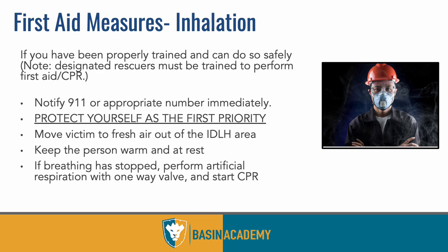Once you get them to fresh air through your rescue techniques, you want to make sure you keep them warm and at rest. And if the person has stopped breathing, you want to give them CPR. Avoid mouth-to-mouth in these situations, because H₂S may be in the air that's in their lungs, and you may be exposed that way as well.